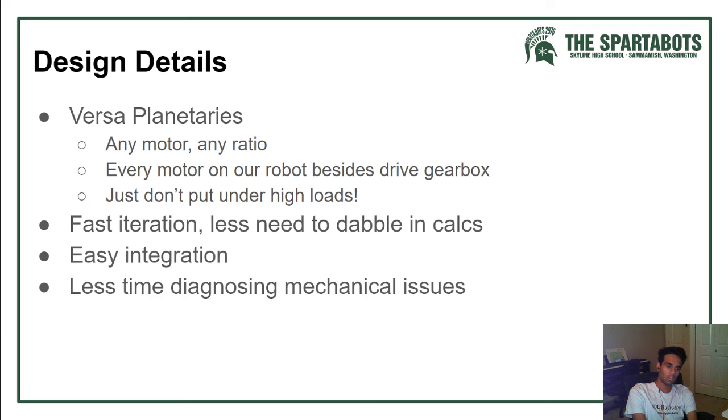This is where the half-inch hole pattern comes in again. Make sure everything fits together. Make sure there's no interference. And so when you design things well, there's less time spent diagnosing these mechanical issues in the future.